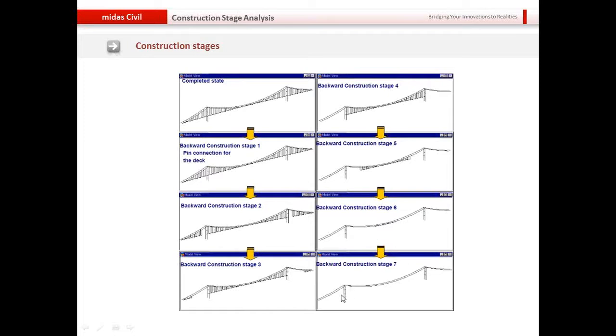So first we'll have the pylons and the cables with the sag there. Then we'll start construction from the sag points and move towards the 2 ends of the pylon. Then the entire span is created, and then we'll move from the 2 extreme ends and start adding deck under these side cables.